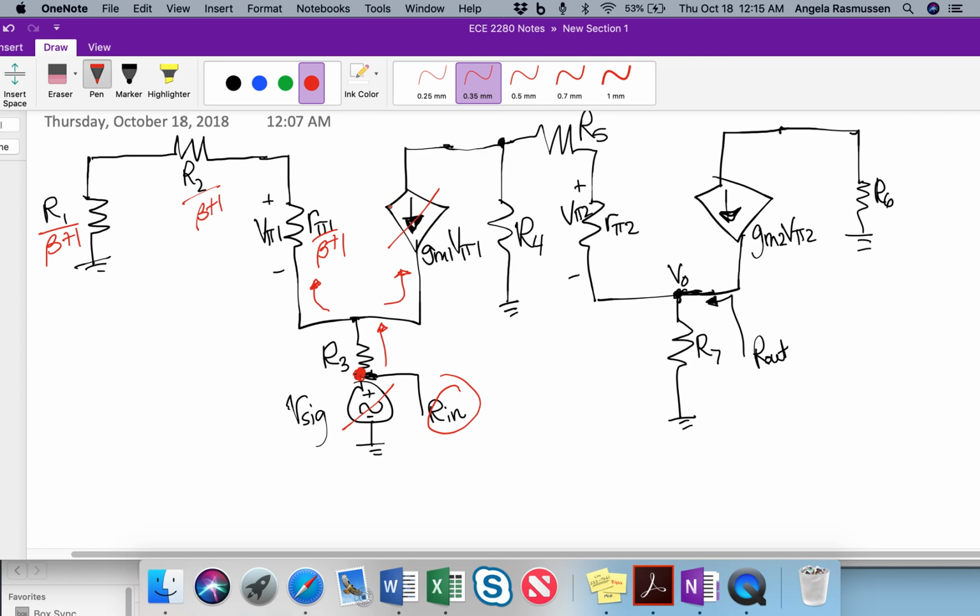which is going to give us the effect from this dependent current source without having to analyze the whole test source on this node. And we can now, by inspection, say what Rn is. So Rn is the pathway from here, and it only has one pathway now to ground, which is going to mean it's going to be the summation of all of those resistors. So R pi 1 plus R2 plus R1 all over beta plus 1. And that would be our value for Rn.